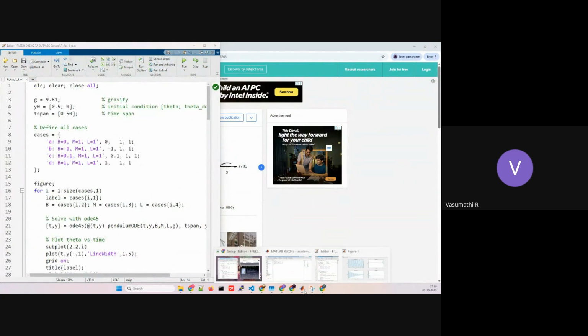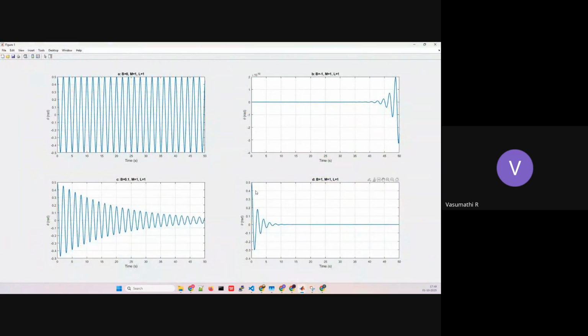Now with this, if I say what an underdamped system would be, it can be oscillatory, not necessarily, but it has some overshoot or some oscillation, but ultimately it is going to settle near the set point, or settle to a finite point. Then I can say it is an underdamped system.